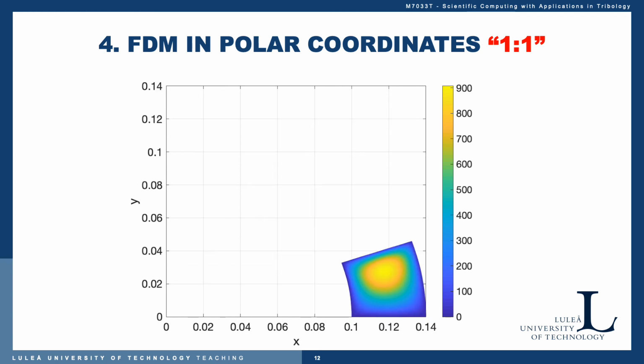But if we then increase the inner radius, maintaining the same aspect ratio as before, we have this problem, and you can see now we have of course changed things to maintain the pressure, and what we have changed is the velocity actually, because in this case the radius is much larger, so we have to lower the angular velocity to have the same velocity over the whole bearing, dragging the fluid in over the segment.